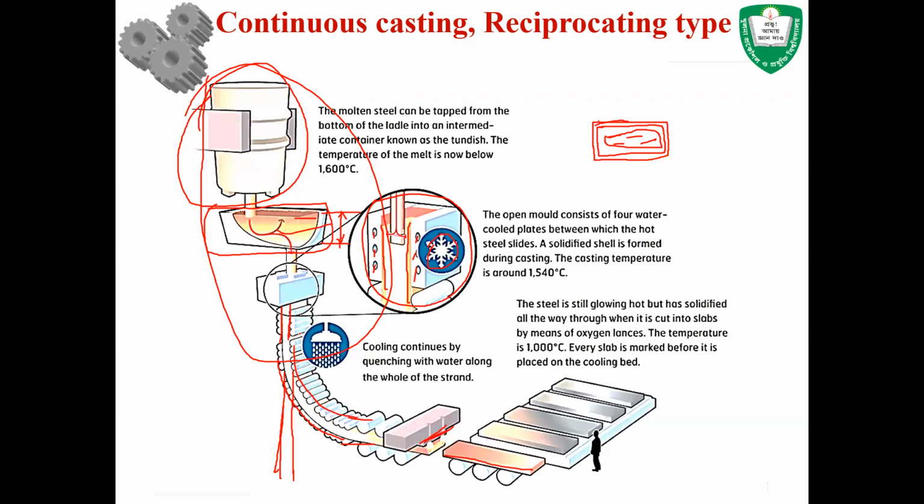So that is why in these roller systems, the cooling mechanism is also applied. That means water is sprayed on these rollers so that the material can get solidified very quickly. And then once the material gets solidified, it gets out of the roller system, and the required size can be cut off from this location. Okay, do you have any questions in here?